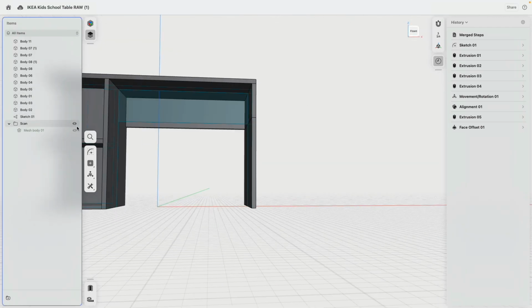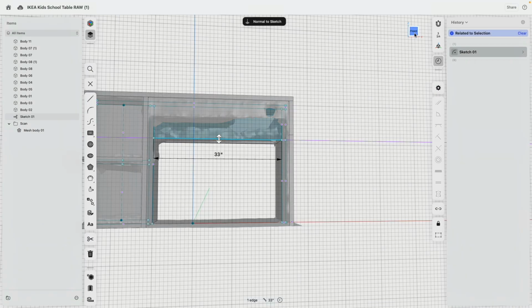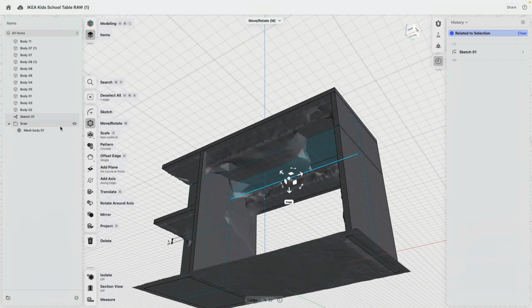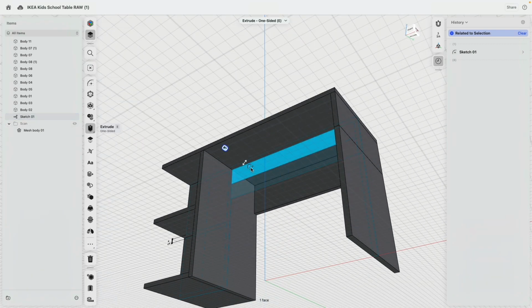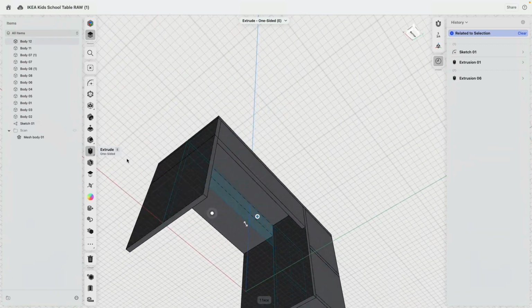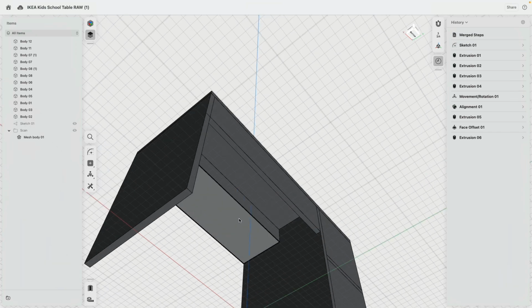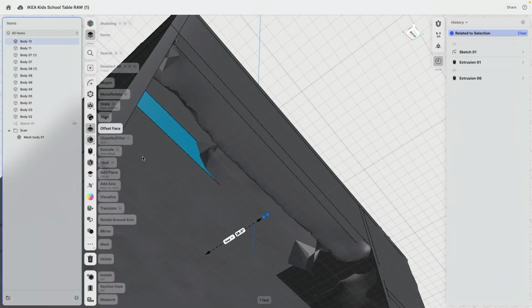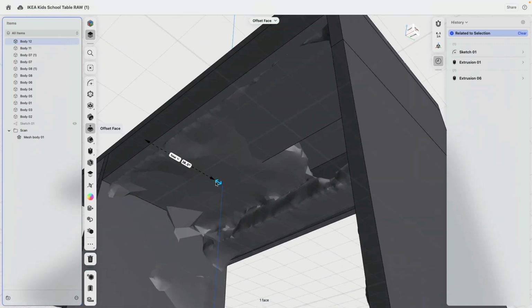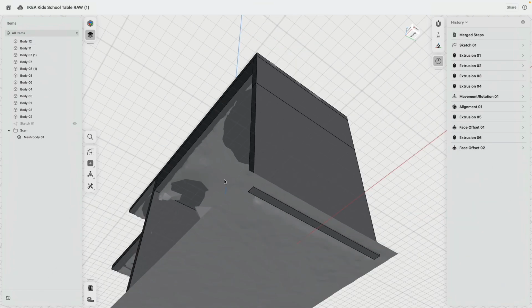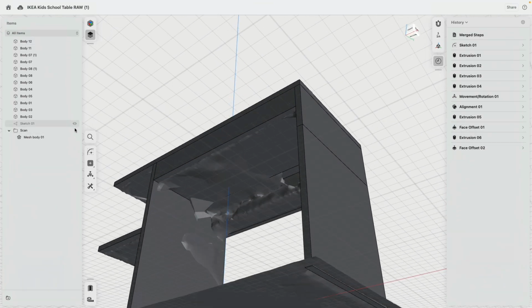Okay, now turn on the sketch again because we need to take a look actually at our drawer. That's also there. Oh, look at that. That drawer conveniently is right at the midpoint. How convenient. Okay. So this one, extrude forward to there. Hide the sketch. No, I don't want to go into sketch mode. Just hide it. And then how far do we push this one back? I don't know. Let's say 13 inches. Okay, beautiful. Cool.